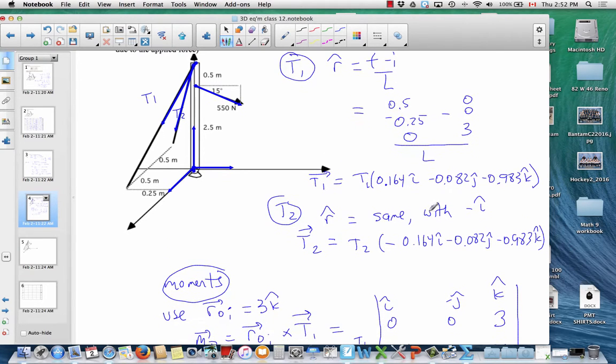Okay, so here's the T1 Cartesian vector. The T2 Cartesian vector will just be the same with a minus I direction. So check your forces, make sure those are right. If they didn't work out right, check that you had the correct final and initial divided by the length. Now here, there's no value in keeping it in exact because you end up with the square root of some decimal number anyway, which isn't useful to carry around. This force is easily enough. We'll just call this one F, so its components are pretty easy, and this is just going to be AX, Y, Z again.